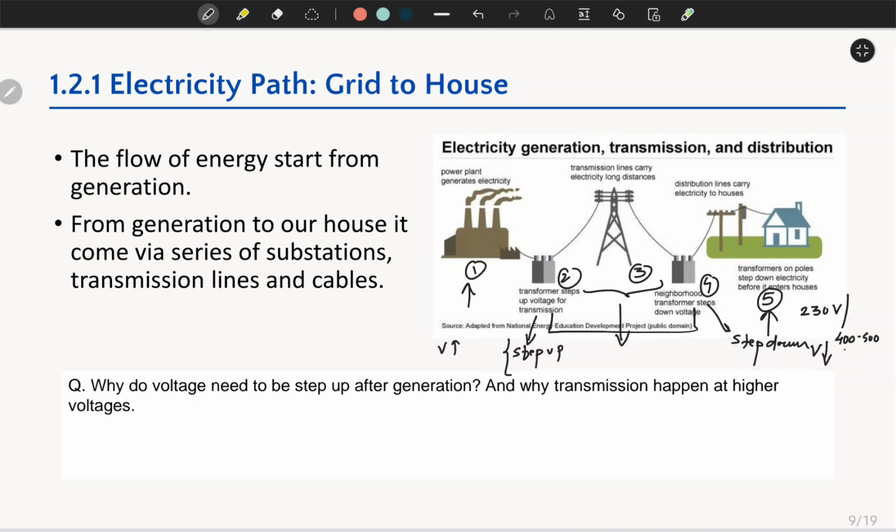So standard wise, 415 is in the IEC standard for three phase, and 480 is in our NEC standard. Now, these are the single phase voltage requirements. So naturally, I need to step down my voltages to meet these levels.